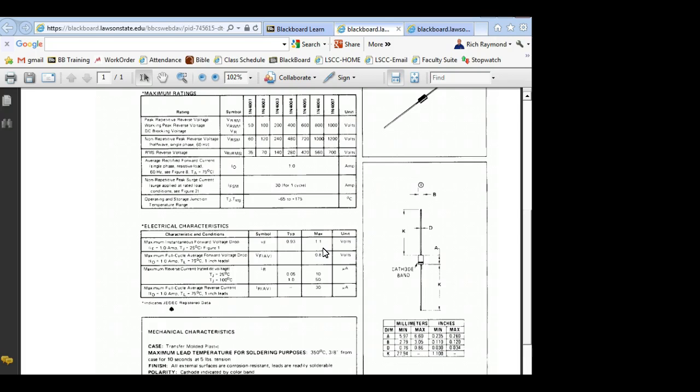So that's why in DC, y'all remember what you had to do in DC? If you had a 1K resistor, what did they want you to do? They wanted you to measure it. And then when you did your back math, you weren't supposed to use the color-coded values. You were supposed to use the measured values, because you were trying to prove our Kirchhoff's laws and our Ohm's laws, right?